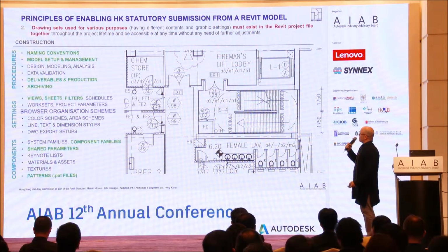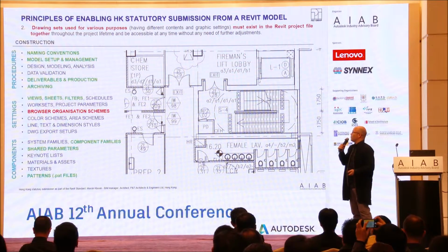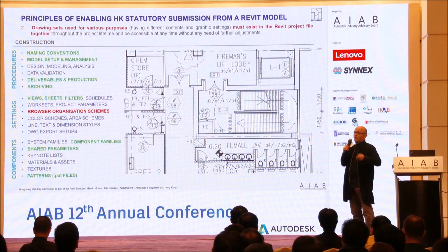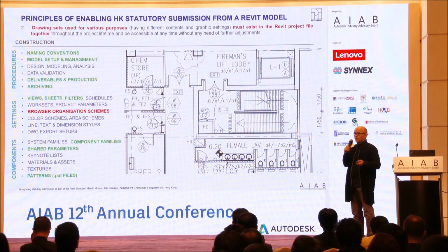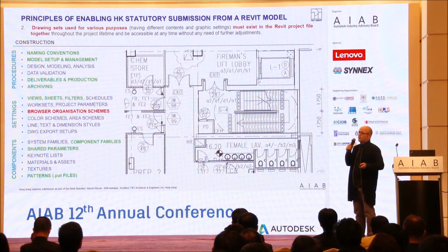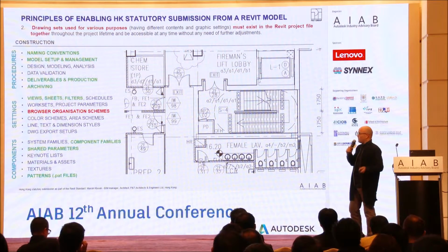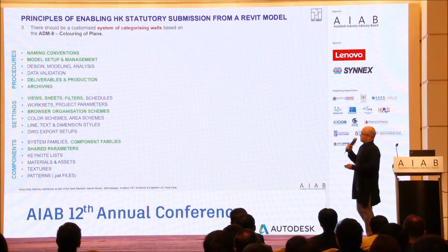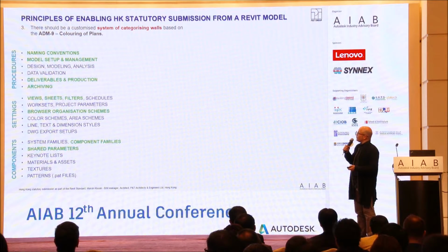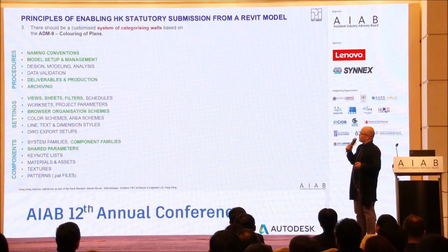And having all these different kinds of plans in the same Revit file, we need browser organization schemes in order to keep some order in our project browser, so that we don't see all those hundreds sometimes of drawings at the same time, but only what we need in a given project stage that we are in. Now, there's more. Condition number 3, first being the different stages, second being different types of plans.